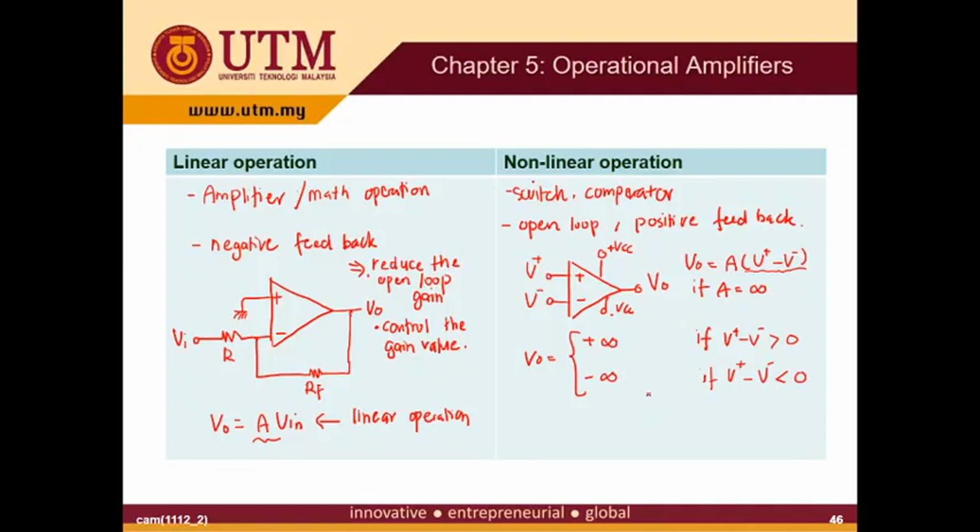So the output voltage here will be limited by plus VCC and negative VCC. Although in terms of the equation V out is equal to plus infinity, in actual operation V out will equal the maximum positive value, plus VCC. For the case of V out equal to negative infinity, it will be limited by negative VCC.